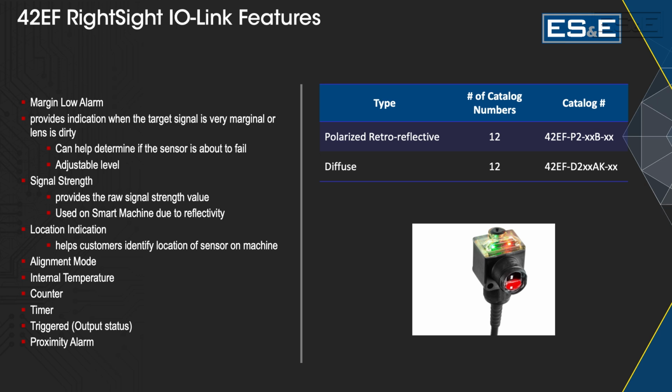So I noticed, is that a stainless steel? It is stainless plate, yes. So, you know, stainless is very bright. Right. Any type of light or cameras or photo eyes, the light shines back into the lens. It makes it hard for it to even recognize if it's there or not.